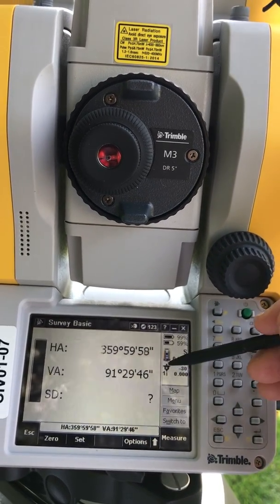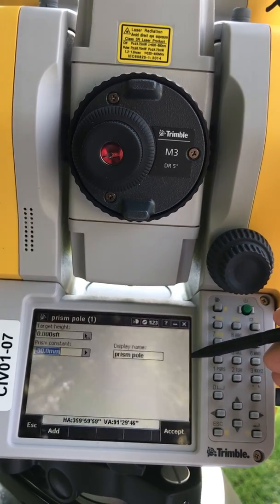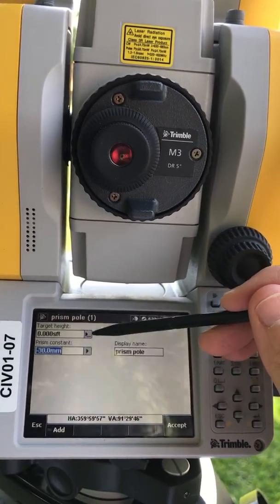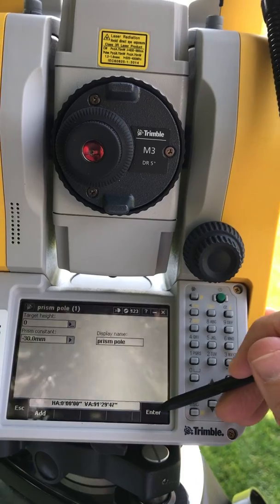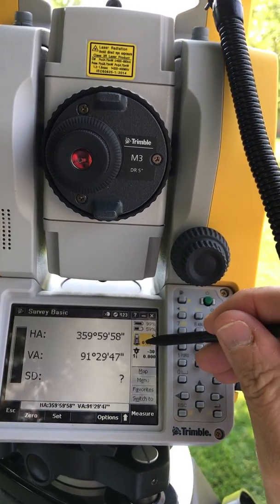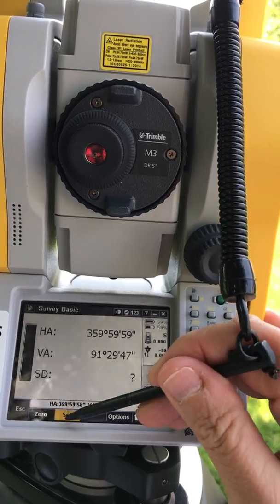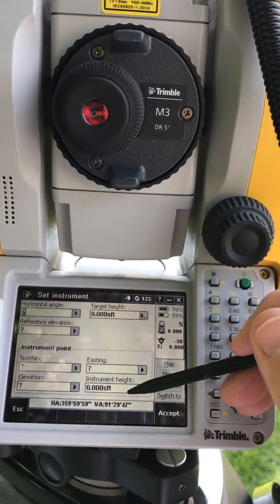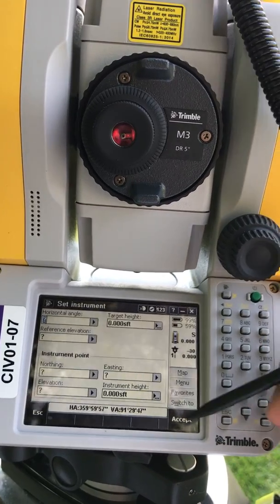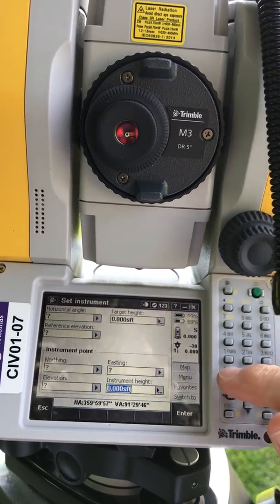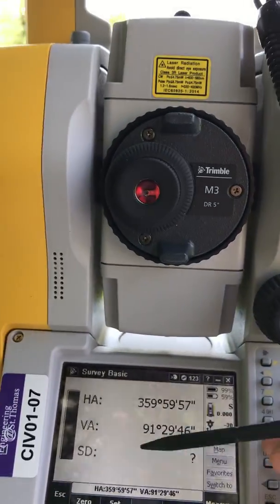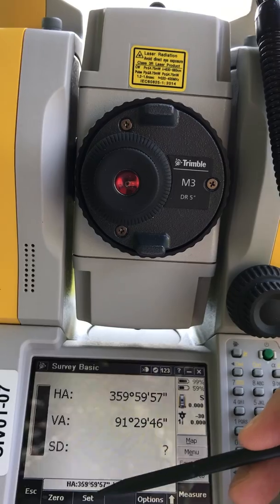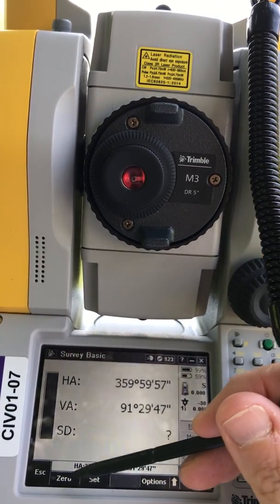We'll accept it. The other thing we need to check is our target height. So we're using -30 for our prism constant, and we've set the target height here 0. If it's not set at 0, make sure that you 0 it out. We'll enter, accept. And the other thing that we're going to look at is set here for our instrument height. So the instrument height we want to set at 0, okay? So if that's not zeroed out, make sure that you press 0, enter, and accept that. Okay, so now we're ready to go ahead and focus in on the target. We've got our target set, and we're ready to, for the very first setting, set this, 0 that out.